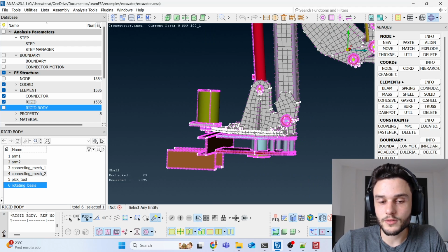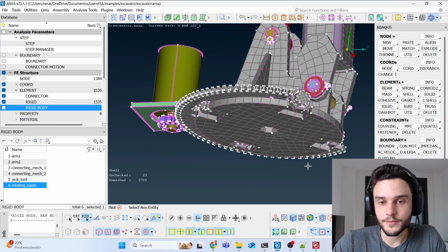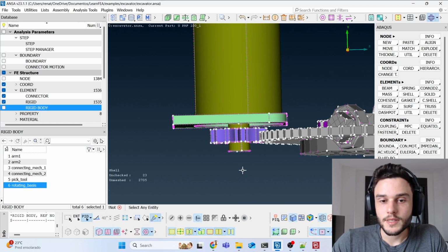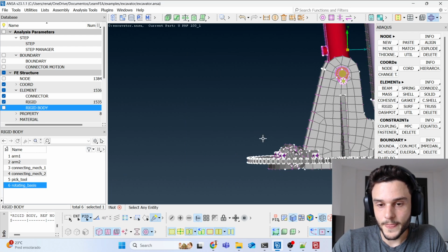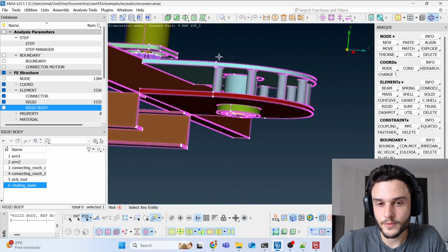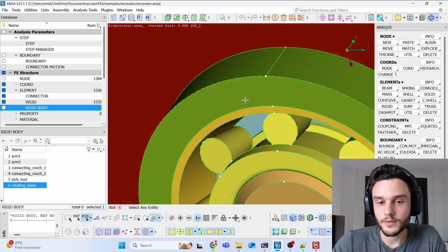So let's use this tool here to isolate by PID, create a box selection like this, so that you're going to get all these parts that are in this region. Zoom in and also select this, and create a box selection like this to get all these parts. Okay, now we have everything that I want. Middle mouse button. See one thing here. Yeah, okay.